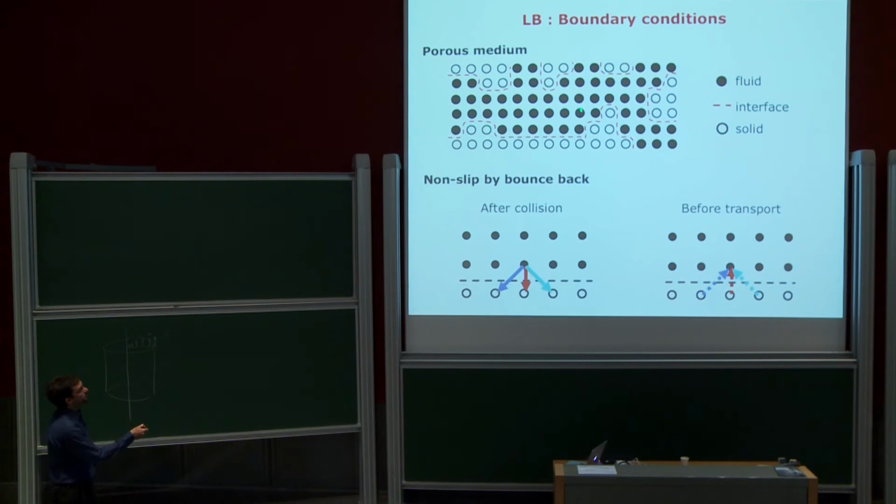At the interface between your fluid and solids, you can implement various boundary conditions. One of them corresponds to the stick boundary conditions. I told you that was the most standard assumption that you make at a solid-liquid interface. And it's very easily implemented in Lattice-Boltzmann by using what is called the bounce back rule. So if after the collision step you have some particles that want to move inside the solid or across the interface,